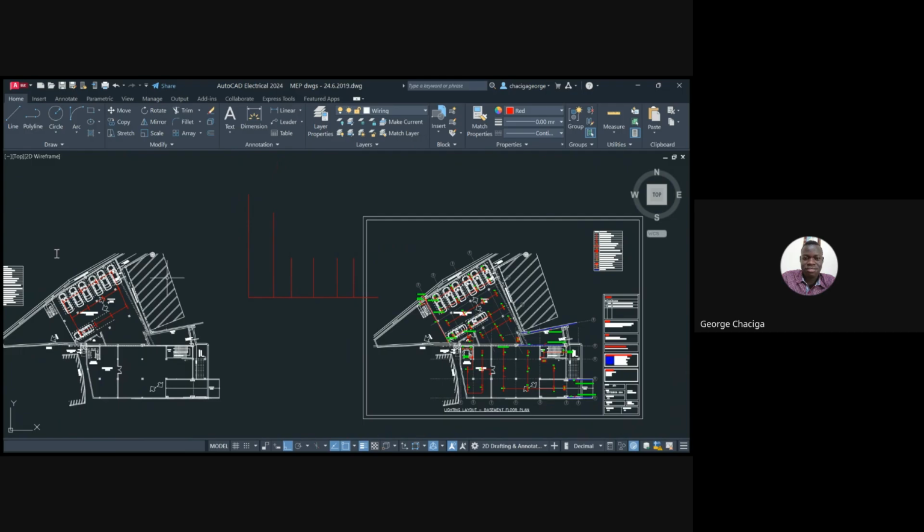The 0.5. Are we together? But there is that first current, the inrush current that has happened at the start, which is literally, in most cases, if you go back and study different lights, that inrush current is 10 times, actually here I have not even demonstrated it well. It is 10 times this what? Normal operating current. So you will see here we've calculated, we've got the 0.5.